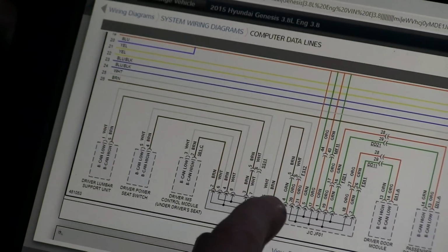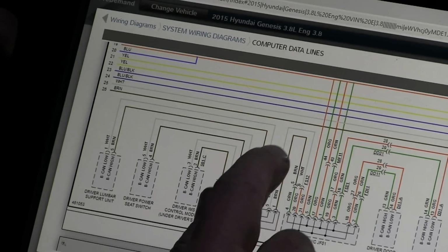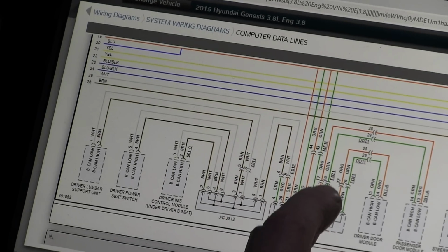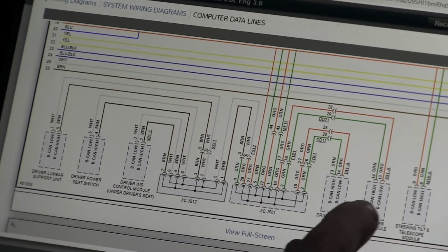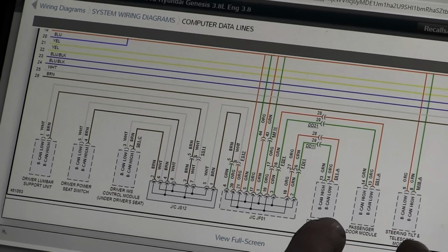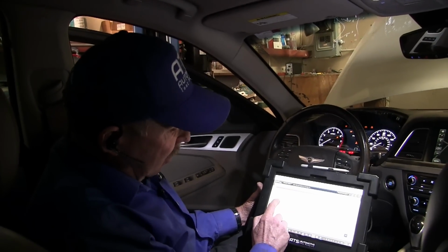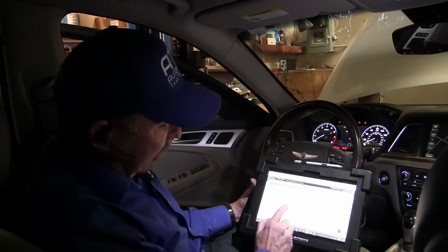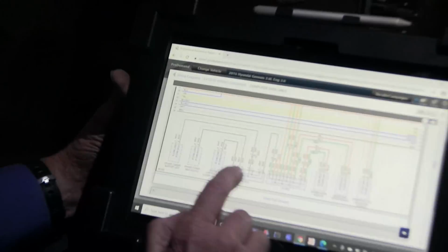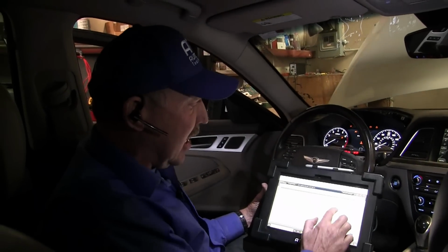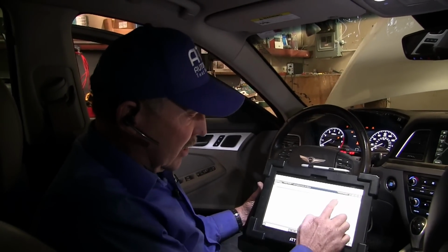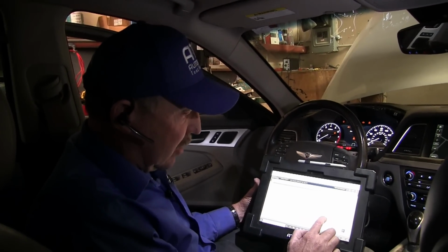Now notice how it comes over. I've got a bunch of brown whites, and then the brown white bridges to a bridge, and then they're going to other medium speed. BCAN is a medium speed. And so then it's coming up here. But if I only looked at brown-white wiring, I might think that these are on the bus that I'm dealing with, and they are not. So just be really careful when you're looking through these and you follow the designations out correctly.